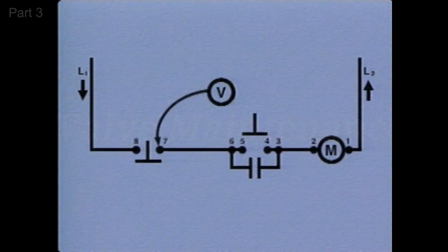So the final test is made from connection point 7 on the other side of the stop button to connection point 4. The voltage tester reading for this test is 0, which means that voltage is unable to reach connection point 7. This reading indicates that the stop button is malfunctioning and is, in effect, open. The problem is now isolated and it can be corrected.